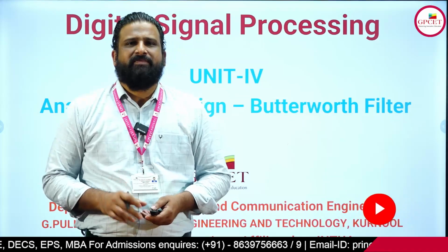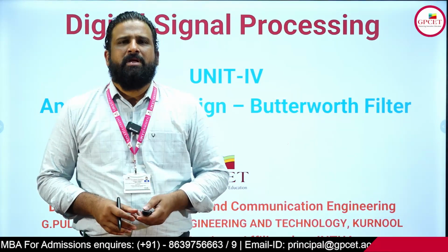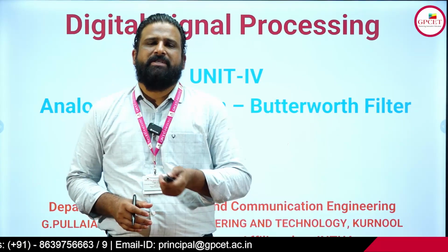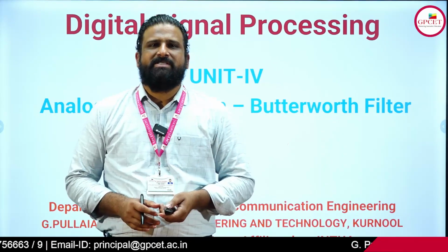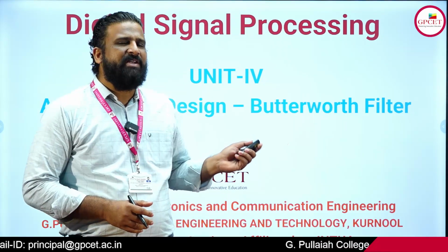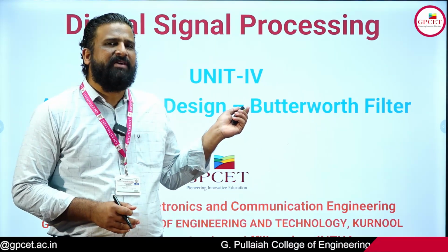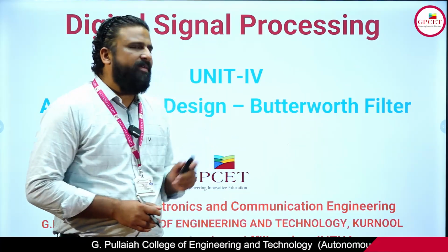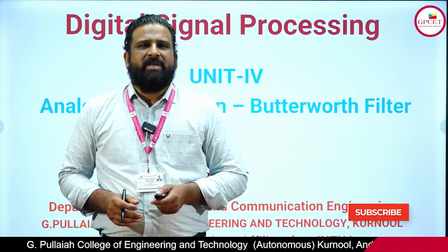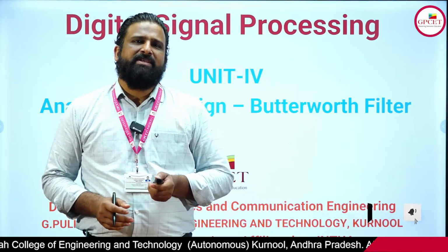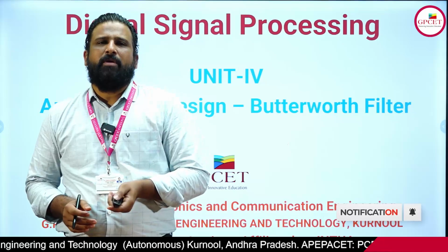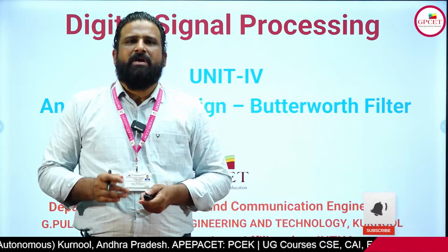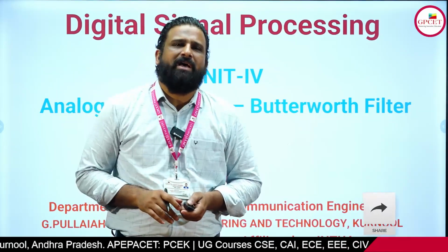where we came to know that converting an analog filter to a digital filter will be simple. That means it can be directly converted from analog to digital in the case of the FIR filter. When we discuss the IIR filter, first the analog filter is designed, and then after that it is reconverted into the digital form. So that is the main difference we have seen between IIR and FIR.